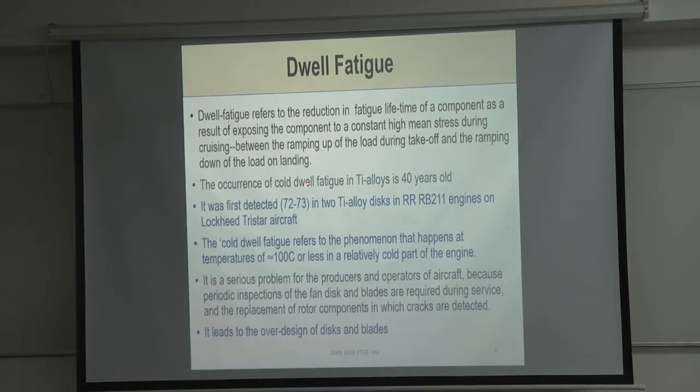This cold dwell fatigue is cold in the sense that in titanium alloys, it can take place around 120 degrees Celsius. That's a pretty cold temperature for a turbine engine. It's relatively cold, right? And it's a 40-year-old problem. It was first observed in some titanium alloy discs, not the turbine discs, but fan discs, in the Rolls-Royce RB211 engines, I don't know exactly what they are, on the Lockheed TriStar aircraft.